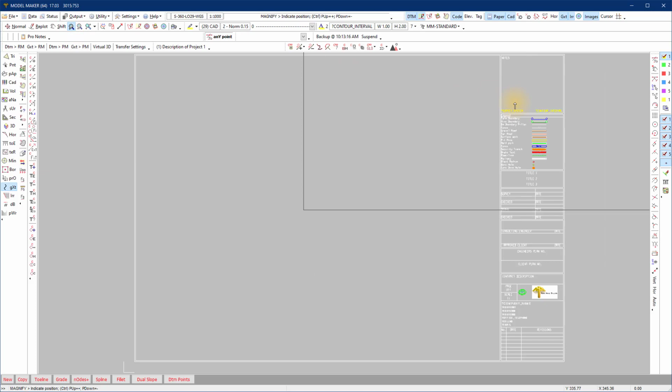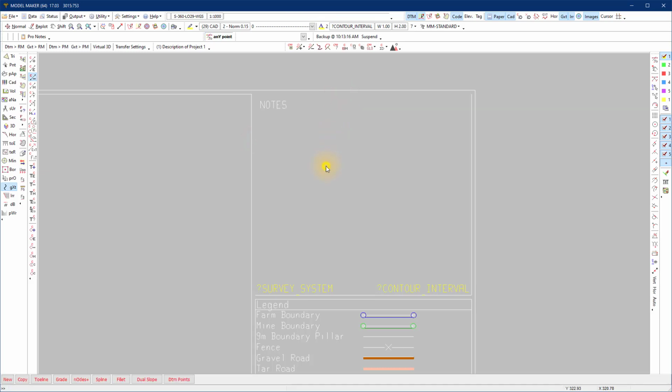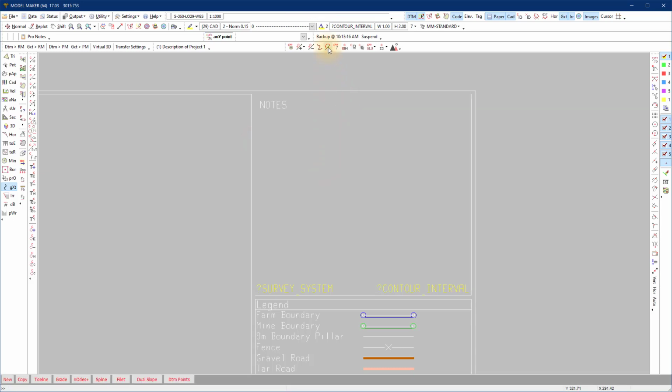While we have the title block loaded, I will now save and invert the title block. Use the invert option when your printable area is not a rectangle and the title block area falls inside the printable area. To do that, I need to make a few changes to illustrate the concept. To create an example, I delete this top part and clean the CAD a bit.